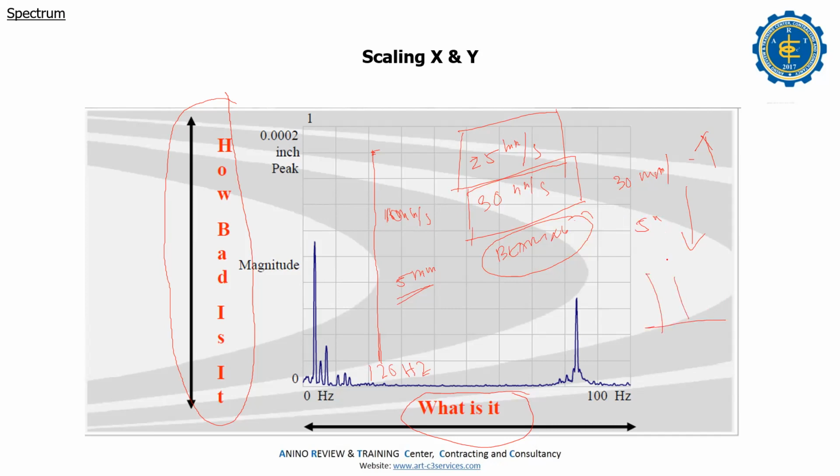If the vibration is 1x only, no problem. But if you have a bearing problem, that's another issue. If you don't have a bearing problem, only 1x, normally this is 25 mm, maybe 20 or 22. That is the 1x, because not only the fan is vibrating, also the structure.